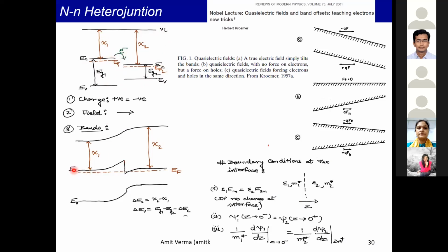So what will happen? The conduction band here, because of the positive slab charge, will change parabolically. Here, it will not be a parabolic variation. Actually, it will be a little bit of accumulation. It's more like a sheet charge, and you get a structure like this. This is the structure that is behind what's known as a modulation doped FET or a high electron mobility transistor.